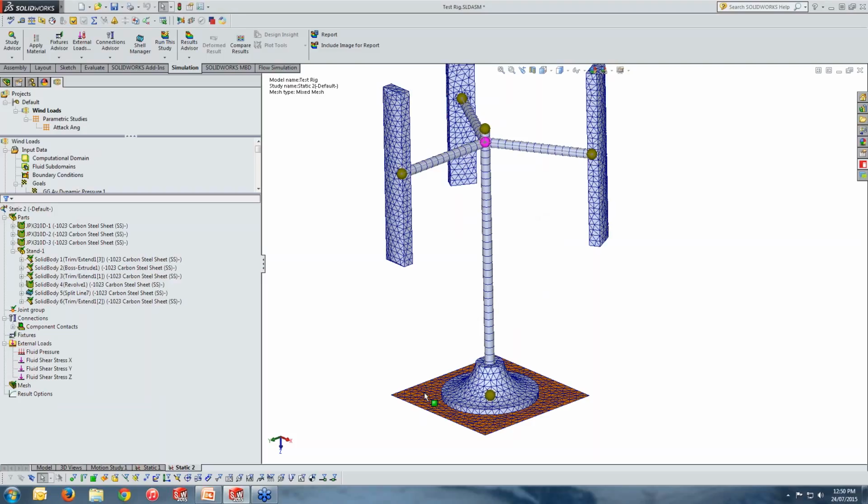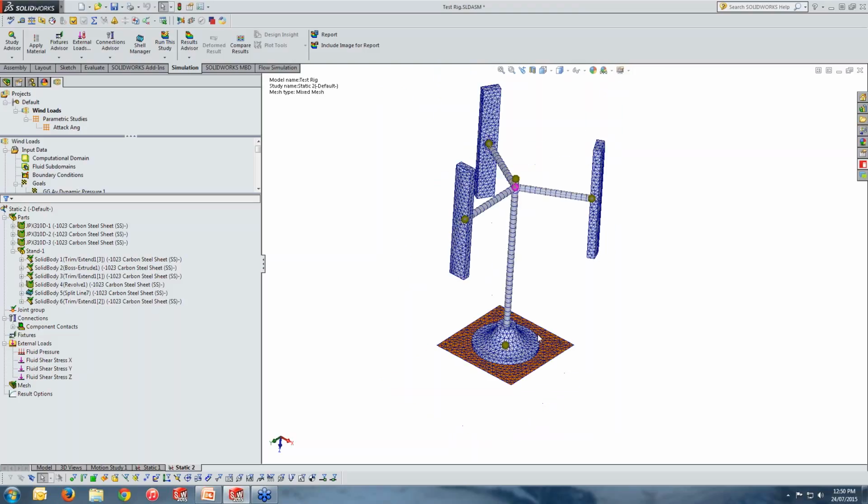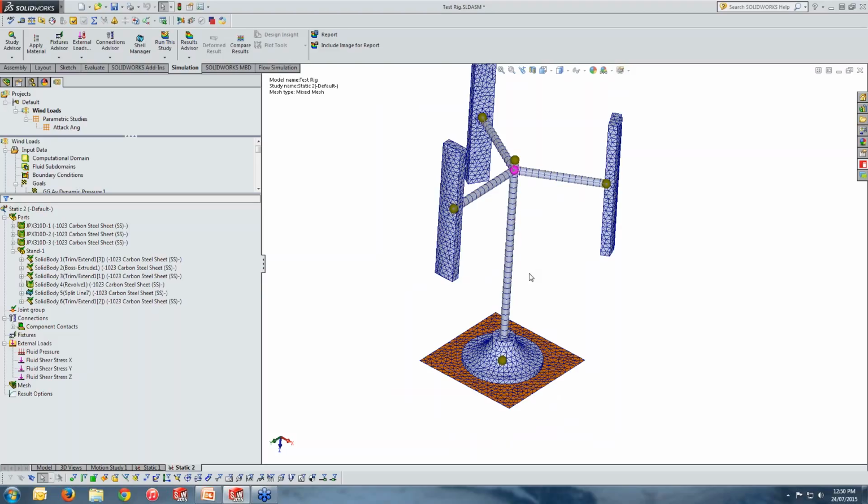Again, like from the flow side, here we have a very important topic of having a very good mesh to converge the answer and capture all important effects. Well, that would be a very separate topic, and we are not going through this, and we're accepting everything here. But one thing for sure, our mesh should be perfect, meaning optimized, not very coarse, not very fine, and it is capturing all the important events happening in our structure.